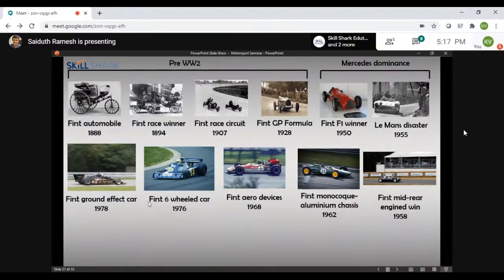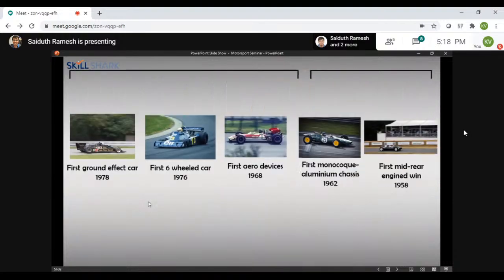The downside to this is the sides of the vehicle are always open. So air would go underneath the car and push out. It would leak out, reducing efficiency. This car had something called a sliding skirt. I think it was a cardboard or wooden plank that used to move up and down along with the road profile. It would literally be dragged on the road. So it's basically like a sealed tunnel at all times. However, this type of aerodynamic device got outlawed very quickly because of its insane power.